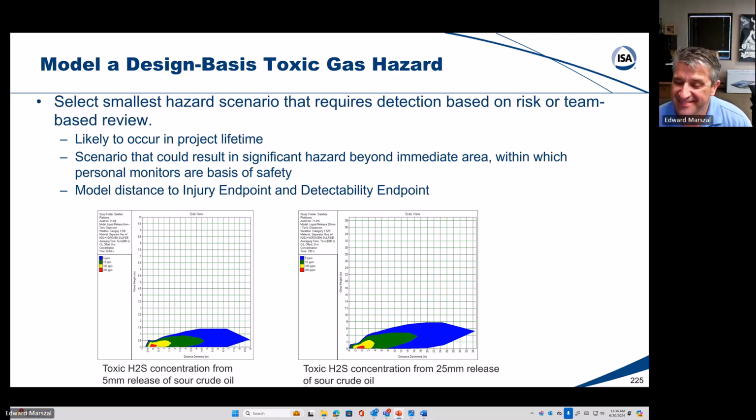Yeah. I just need to get so-called expert advice. What is the acceptable, tolerable region? Good practice is plus minus 1 meter, right? For gas detection. Even the same also for fire detection, is it? Yeah, we allow 1 meter on fire detection.